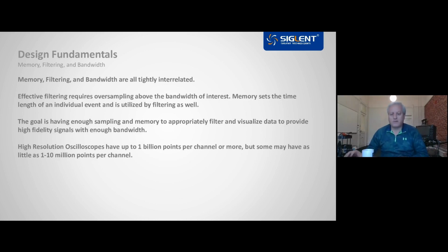Most applications, though, even for performance scopes, don't require max bandwidth for most measurements. This is where the memory can be used flexibly and purposed specifically to an application. We'll talk a little bit about memory-focused application spaces later. But here, we can use filtering techniques to trade memory, sample rate, and bandwidth for increased signal fidelity, and this can often be expressed as increased resolution. The vast majority of applications really fall into this middle ground, where maximized signal fidelity is the goal. We can utilize the memory and the sample rate in exchange.